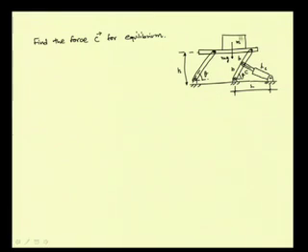If you would like to solve this problem by the conventional method of force and moment equilibrium equations, then you will see that it is not possible to find this force C from this given data, because we do not know the position of this mass on this platform. That means its horizontal position with respect to these joints or with respect to the edges of this platform is not known.